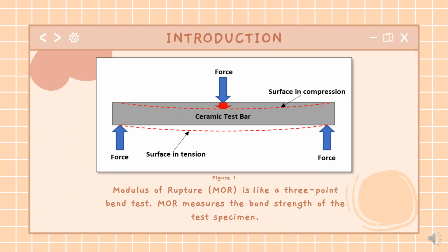One way to determine how strong a material is, is to measure how easy it is to break it. Modulus of rupture, frequently abbreviated as MOR, sometimes referred to as bending strength, is a measure of a specimen's strength before rupture. It is also known as flexural strength, bend strength, or fracture strength. The modulus of rupture of a material differs from its tensile strength in that it defines the maximum stress that a material can withstand before undergoing severe deformation due to stretching. The two properties are intrinsically linked.